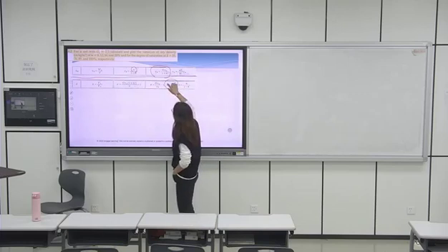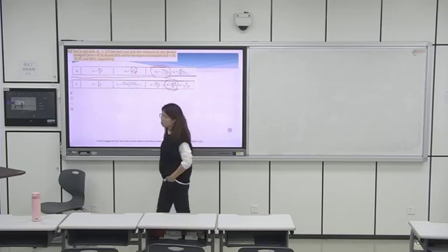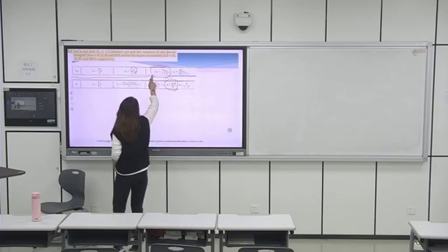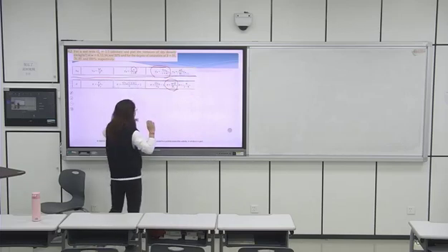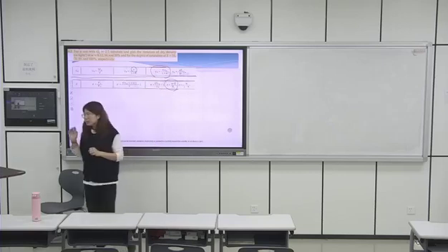Then put this void ratio in here, and we can calculate the dry density for the different water contents and saturation degrees. So the relationship we need to use is this first, and then this. Let's see the answer.